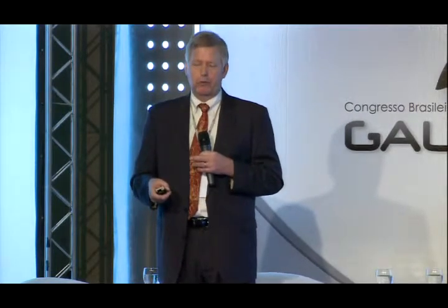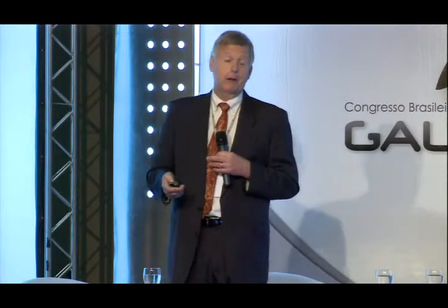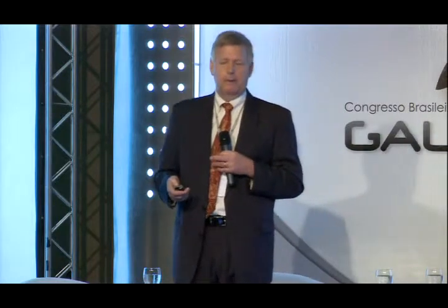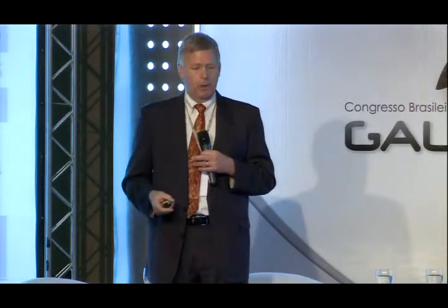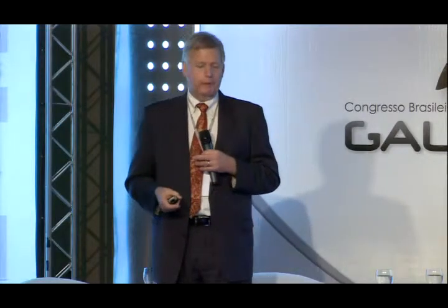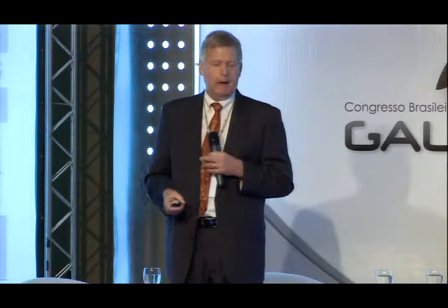And then maintenance repaint at 5% rust for the paint. So if this is not ideal, this is practical. You wait till 5% rust and then you paint. And then for the galvanized in the mild industrial environment, we say it's 50 years life for the galvanized coating. So then, of course, you have these numbers, which are completely in favor of hot dip galvanizing.